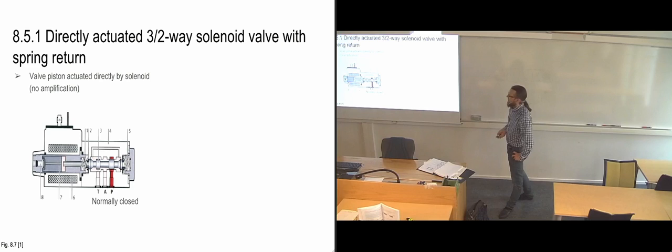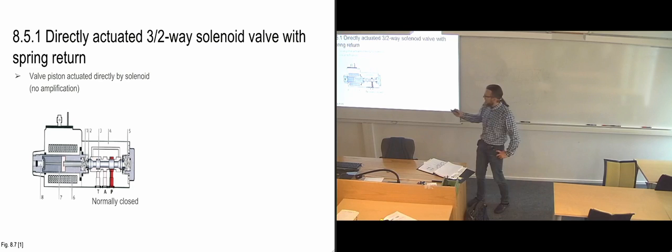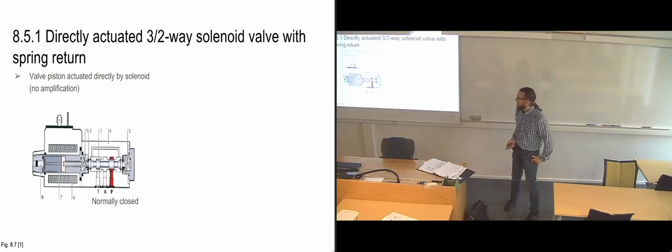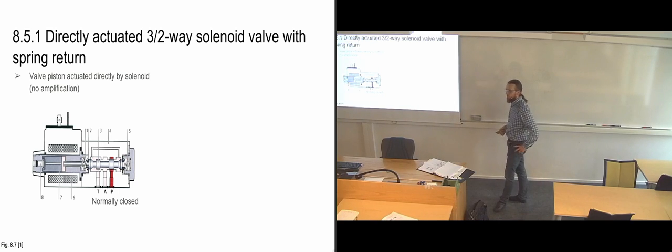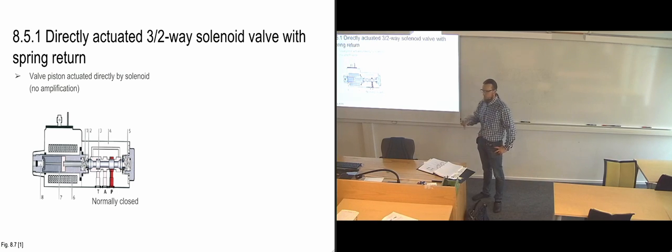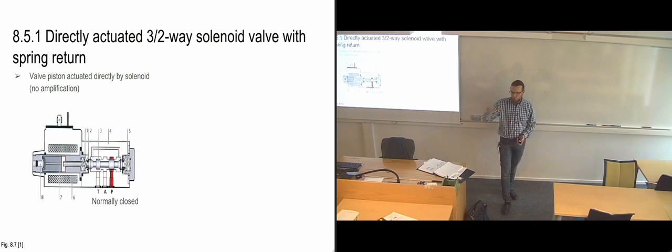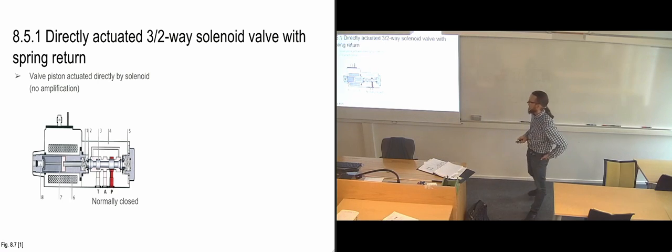This is a typical solenoid valve, where you can see the valve itself isn't really big, but the solenoid part is just as big as the valve housing. So it takes some room with all of these electrical coils that you use as electromagnets. That's basically what this area is, just loads and loads of copper wire that's been coiled, creating an electromagnet.